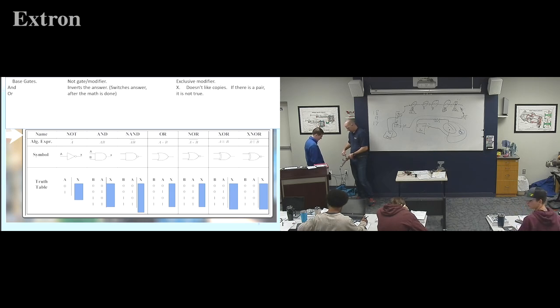Now the amperage can flow through, even better. Now it takes work to flow through. Look at this. I would have a voltage on each one. If I burn out a light bulb, now I don't have amperage going through because it can't go through the wire. So at this point, if I were to measure my voltage across here, I'd have the voltage drop. I got all the pressure from this side, and on this side, I have the negative side coming through, and there's no amperage anywhere, right? So there's no amperage here, so I'd have the full 12 volts trying to jump across there.